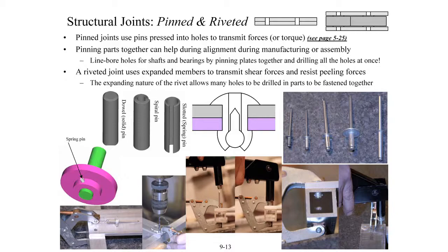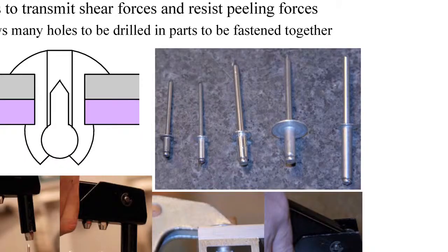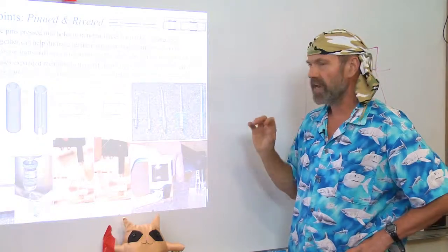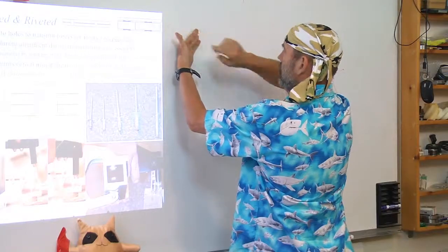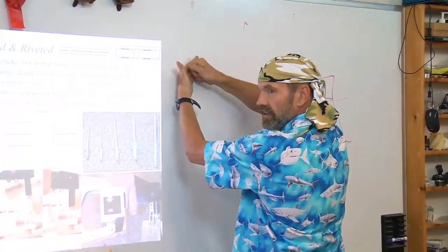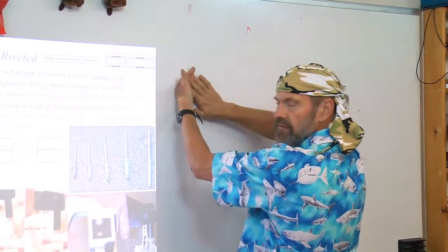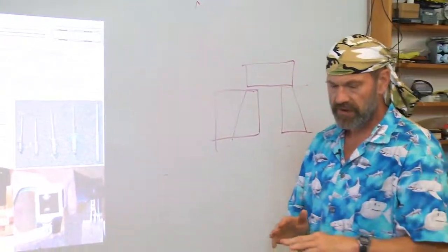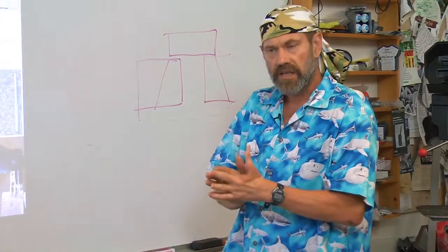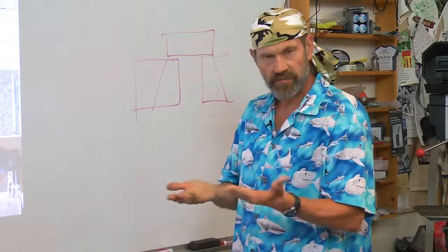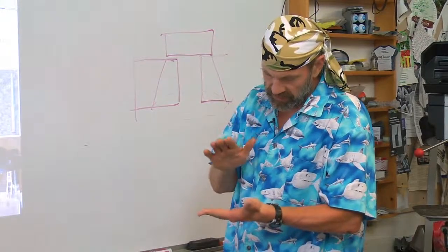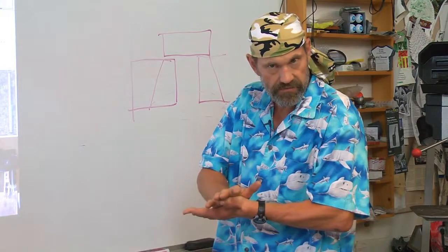Now, when would I rivet something versus bolt it? Well, rivets can be very easily applied and are much cheaper than a bolt in general. You can apply a rivet through a blind hole. That is, you can have two parts together, drill the hole, put the rivet in, and rivet it without having to get access to the backside. Rivets also have the ability, if the holes aren't perfectly aligned, to expand and fill the material in the holes. Bolted joints, remember, work by clamping together.